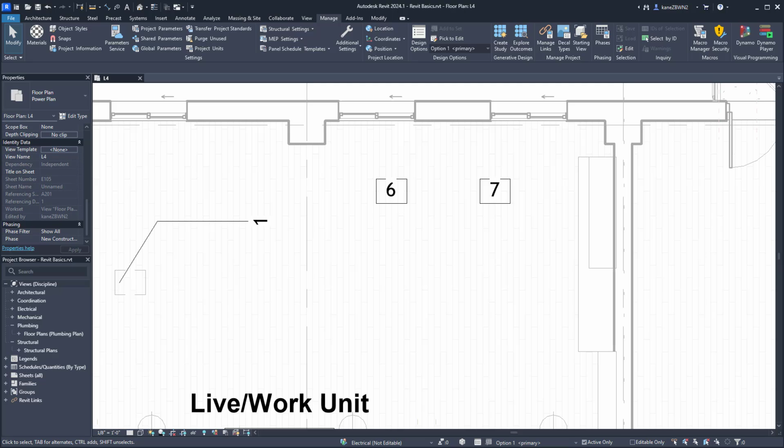So I mentioned the primary tag has another use beyond determining which option in the option set is visible when you're in the main model. When you've decided which of these options you want to stick with, you can tell Revit to merge everything from that primary option into the main model. To do that, we need to go back into the Design Options command.